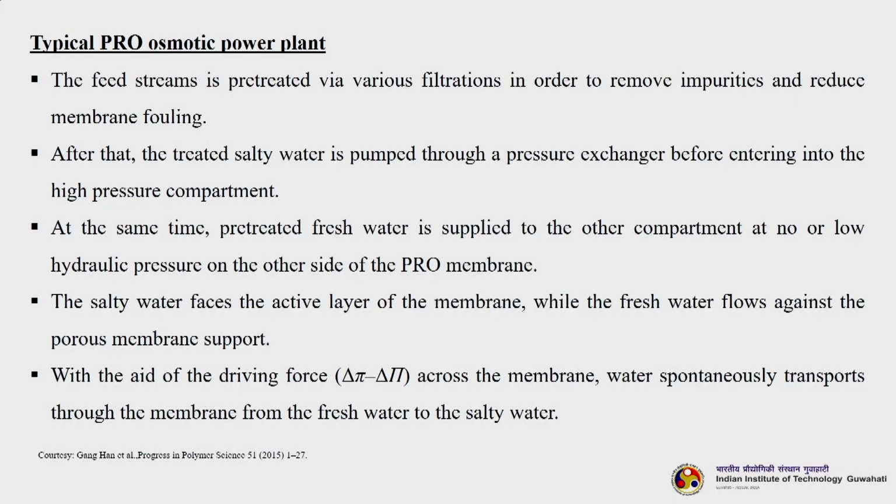After that, the treated salty water is pumped through a pressure exchanger before entering the high pressure compartment. At the same time, pre-treated fresh water is supplied to the other compartment at no or low hydraulic pressure on the other side of the PRO membrane. The salty water faces the active layer of the membrane, while the fresh water flows against the porous membrane support. With the aid of the driving force, delta pi minus delta p, across the membrane, water spontaneously transports through the membrane from fresh water to salty water.